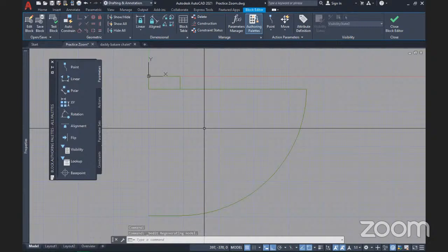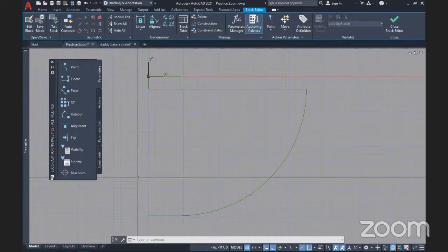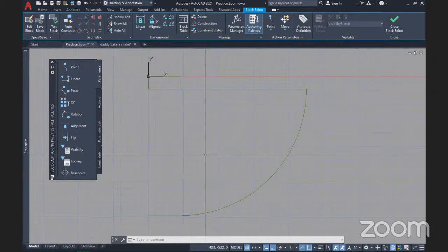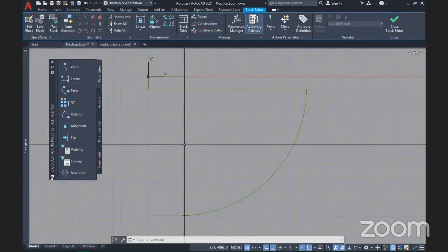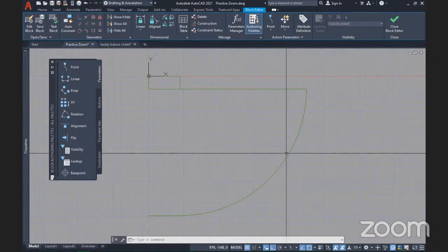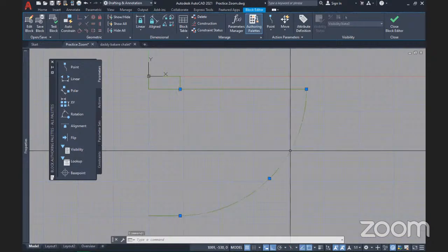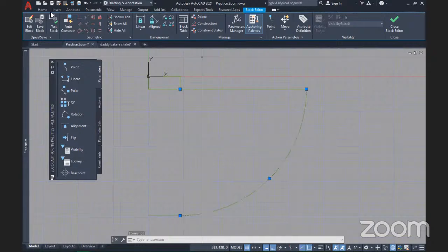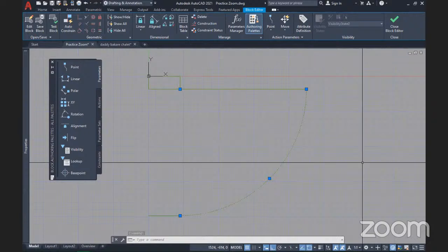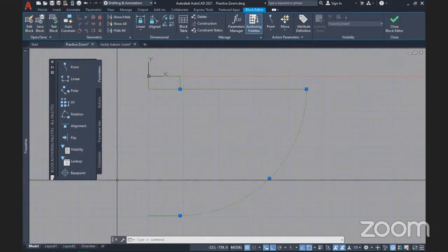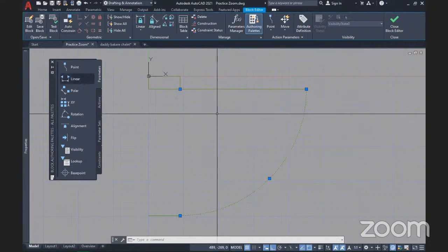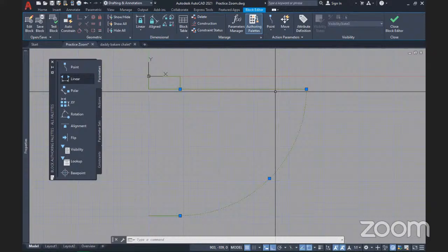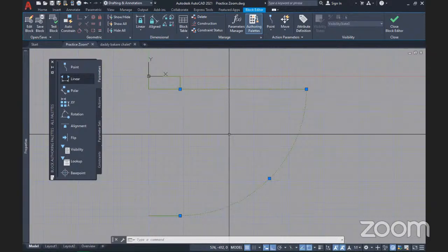So right here, I can actually edit the elements of this door. I can decide to say, okay, I want to make it a little bit fanciful. I want to make this line dotted. You can go and change the line type and make it the way you want, or add some other things. Let's say I want to create a line.